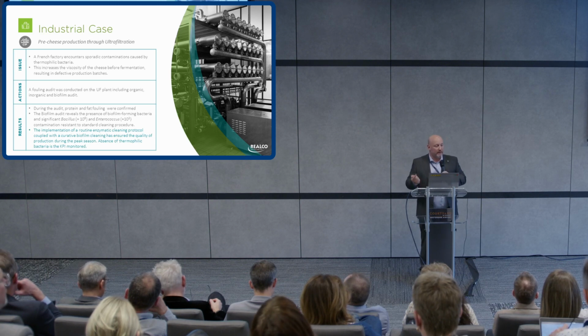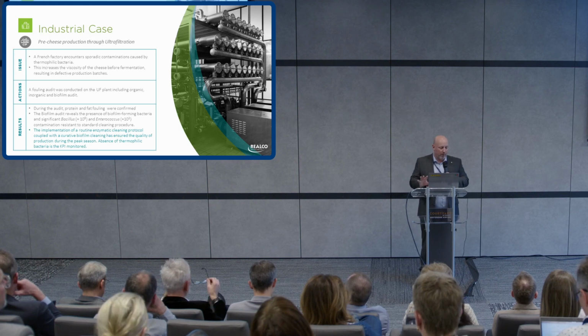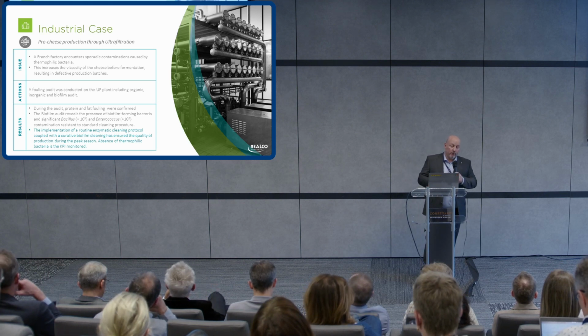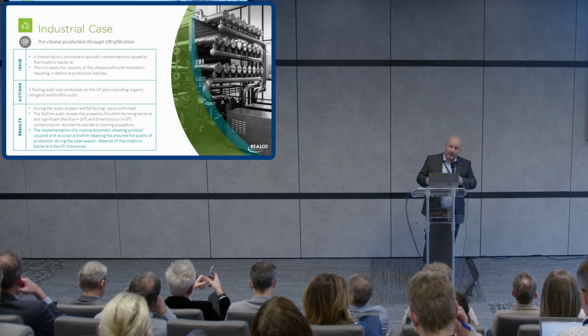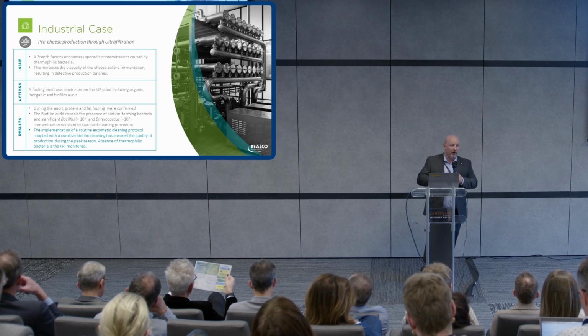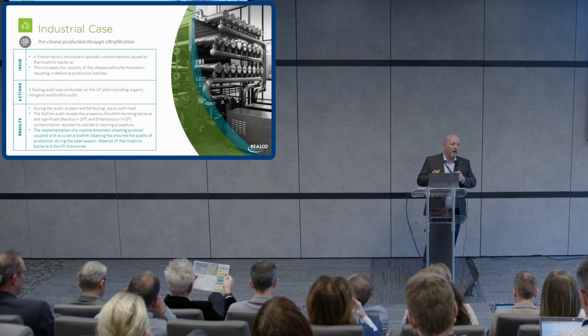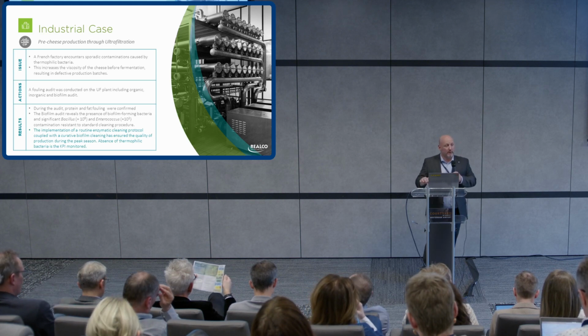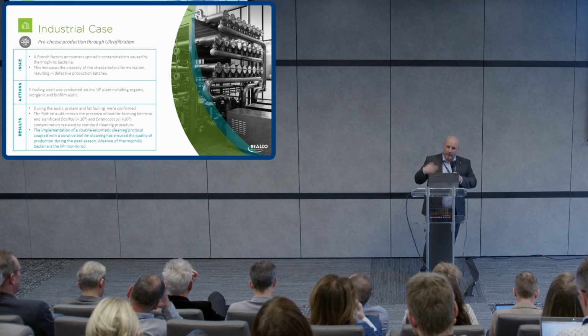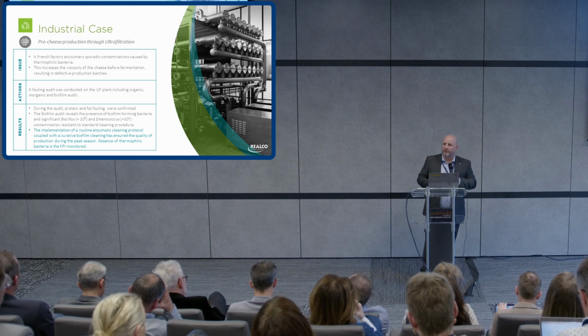And you can see that since we implemented the treatment, they have no problem anymore. And here they are following the efficacy of the treatment thanks to the thermophilic bacteria that they can follow. So they can monitor those kinds of bacteria, and it's a good tool for them to say, okay, as long as we are okay with the thermophilic bacteria, we are controlling the biofilm. When it goes up, we have to do the biofilm treatment. So here they have a KPI to monitor.